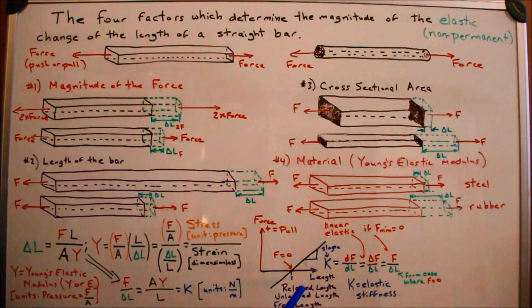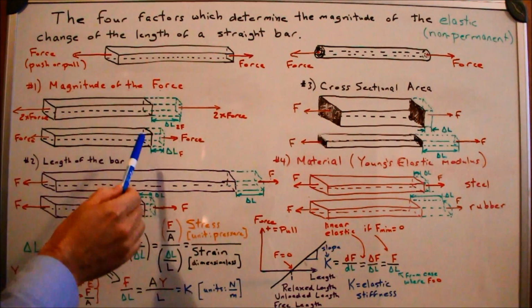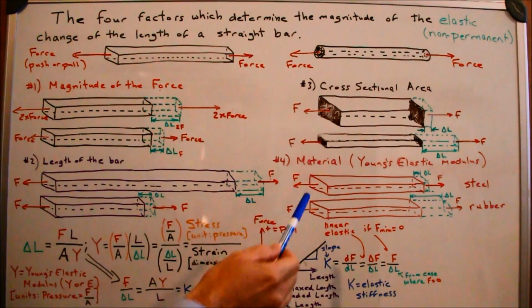Slope then relates the change, so slope is the derivative. In starting courses, you're pretty much always going to assume this is linear, but truly it's the derivative, so the tangent point, whatever load I'm in. If it's linear elastic, then it'll be a linear relationship, but it's the derivative of the change in the force divided by the change in length. So it relates this characteristic, with everything else being fixed for this case.